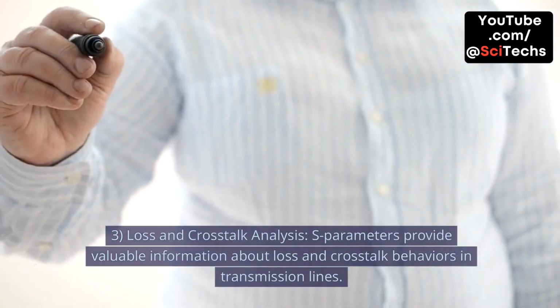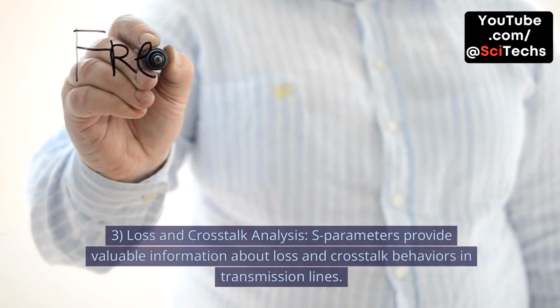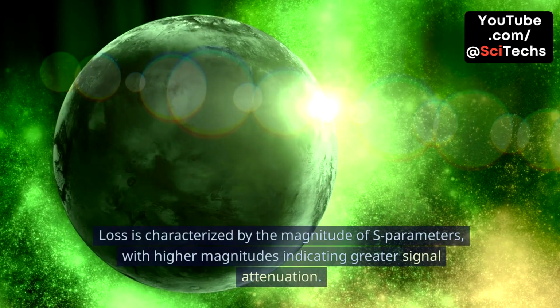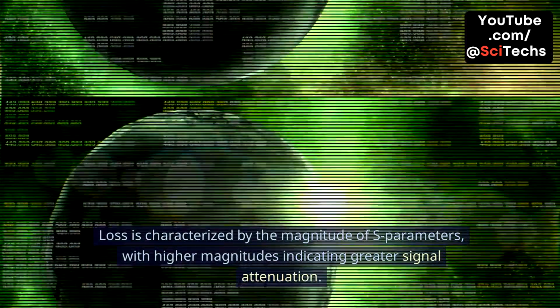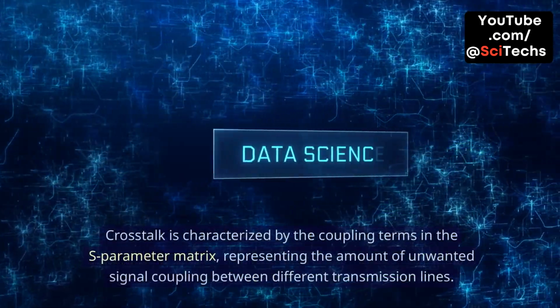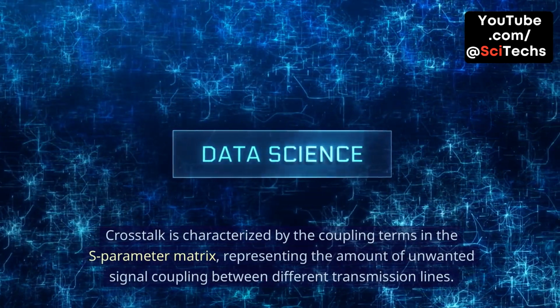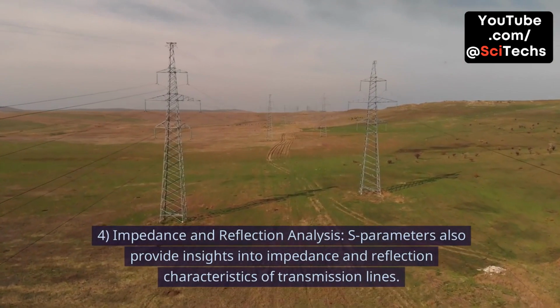3. Loss and crosstalk analysis. S-parameters provide valuable information about loss and crosstalk behaviors in transmission lines. Loss is characterized by the magnitude of S-parameters, with higher magnitudes indicating greater signal attenuation. Crosstalk is characterized by the coupling terms in the S-parameter matrix, representing the amount of unwanted signal coupling between different transmission lines.